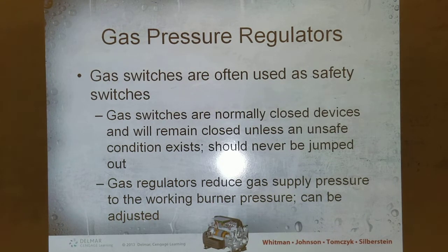Gas pressure regulators. Gas switches are often used as safety switches. Gas switches are normally closed devices and will remain closed unless an unsafe condition exists. Should never be jumped out. Gas regulators reduce gas supply pressure to the working burner pressure and can be adjusted.